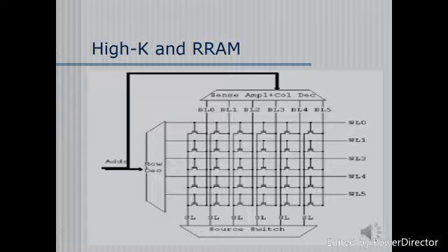When modified, the structure created will look like a single plane, and the coupling capacitance will be lost. When this happens, the sidewalls start to break down and lose their coupling factor. A solution to this is high kappa dielectrics. Research today is trying to switch out the stacks of ONO as inter-polysilicon dielectric to create larger coupling factors in the gate.